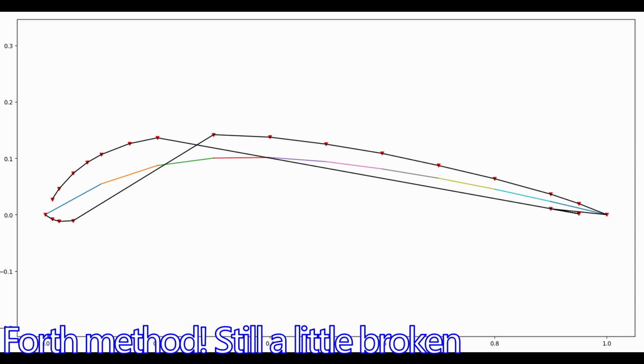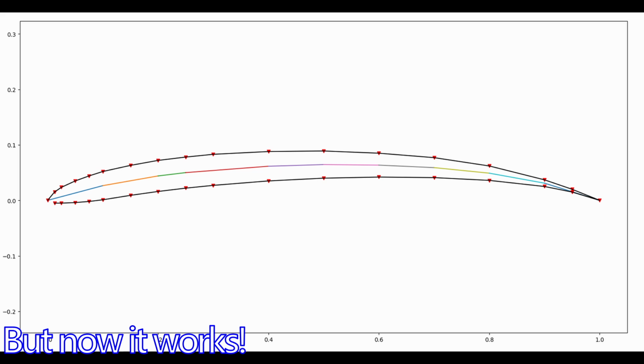In this method, I subdivide the domain into a bunch of central lines through the cross section. These central lines define top and bottom. That way I don't transition from the top to the bottom too early, which is one of the issues I had with highly cambered or thin airfoils. It would suddenly transition from the top to the bottom.